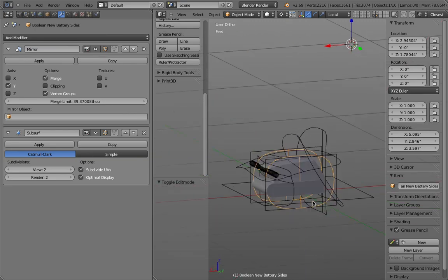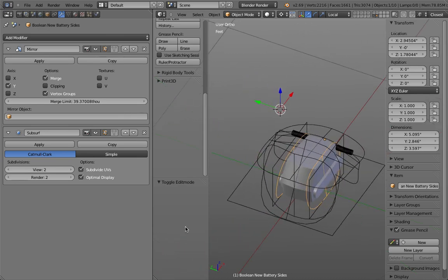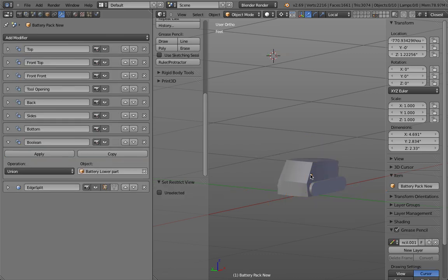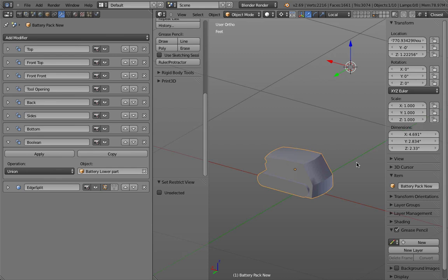In all these surfaces, we would, for example, bring into Fusion, turn those polygon surfaces into T-spline, which is a different technology, and then the T-spline we will convert into NURBS surfaces, and then instead of Boolean modifying, we will use trim commands, which is kind of like a scissor. So we start cutting all the surfaces. So we as well just end up, for example, with this. And then with a NURBS feature, we can round those edges.